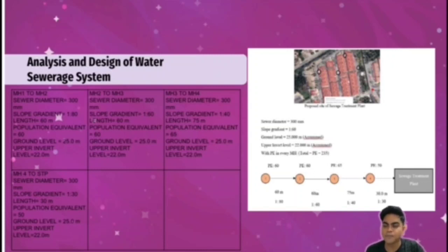The sewerage system is designed to carry all the sewage flow, including sewage to the approved disposal point. Sewer pipe should not be constructed on a slope or within the slope failure envelope. So in the event where it is unavoidable, the said structure must be designed not to encounter settlement and at no time be at risk of collapse during its operating lifespan.